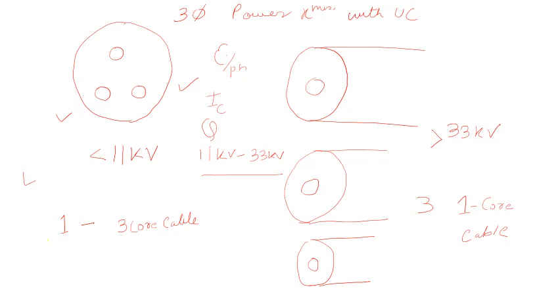The characteristic impedance is more inductive in an overhead transmission line, and for cables it is more on the capacitive side. So we are more focused on calculating the capacitance, charging current, and the reactive part. We have already seen most of the parameters for a single core cable. Now we will go for a three core cable.